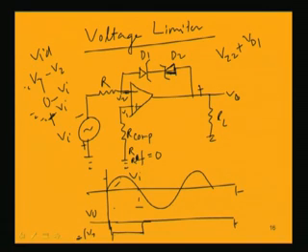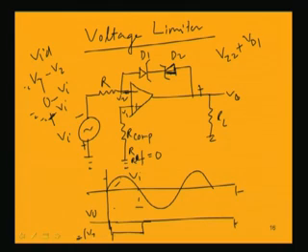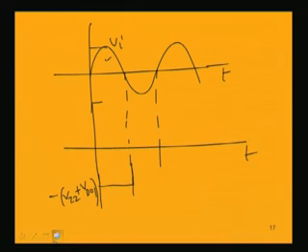So, now breakdown will be here in the D1, and D2 will be acting as a normal, ordinary diode, which will have the normal diode drop of VD naught 2. So, we will be getting a positive voltage Vz1 plus VD naught 2 for the negative half cycle. So, it will be like this.